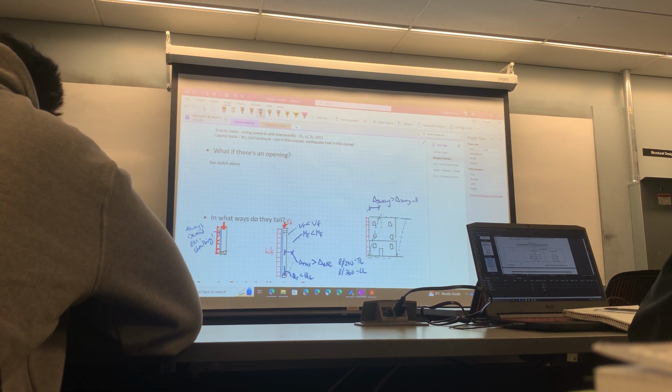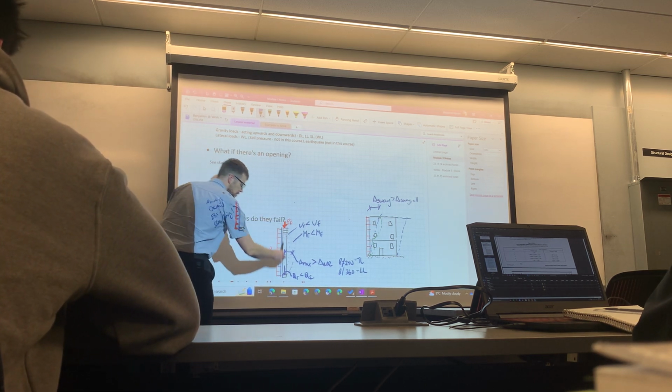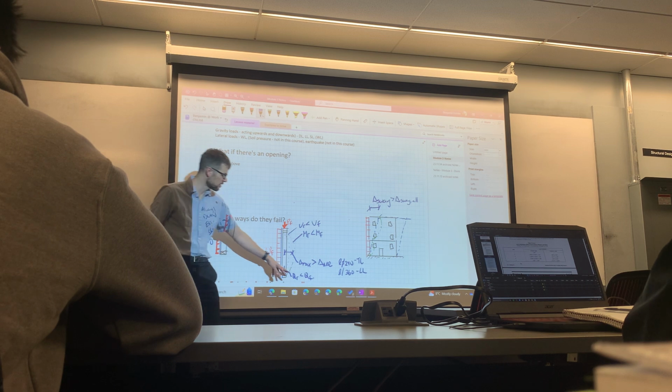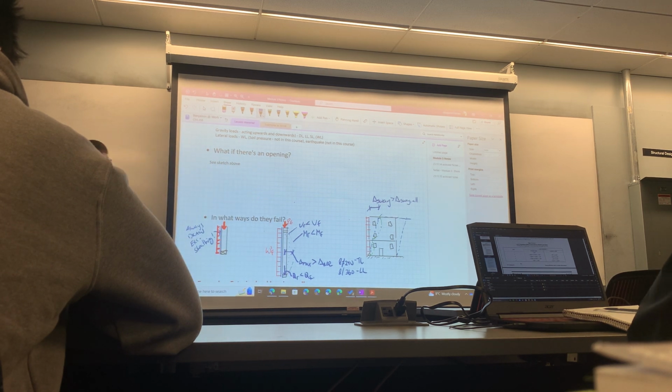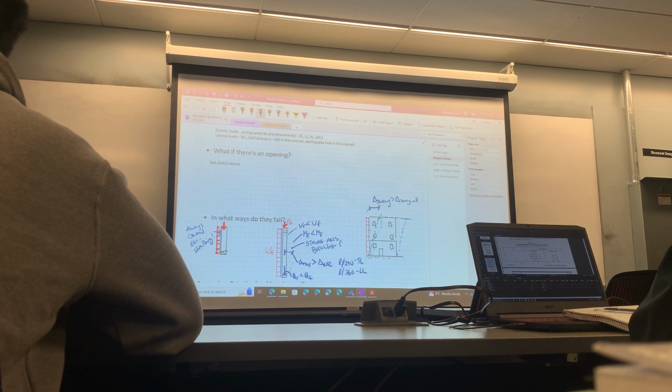So everything we're focusing on, we got bending members like a joist. That's good. We've got some compression parallel to the grain type failures with QR. What else with compression failures? We talked about it already. Strong axis buckling, right? So basically we're talking about PR is less than PF.